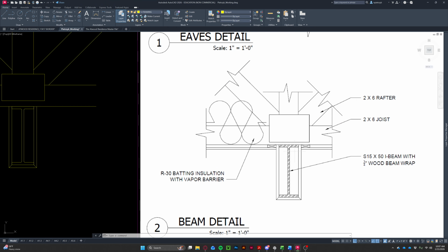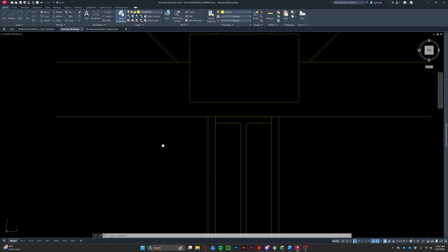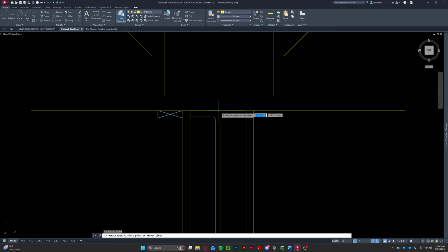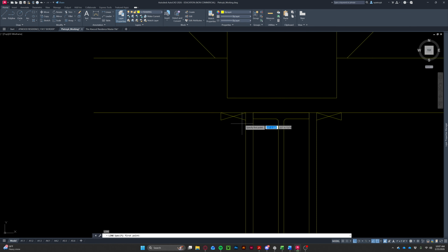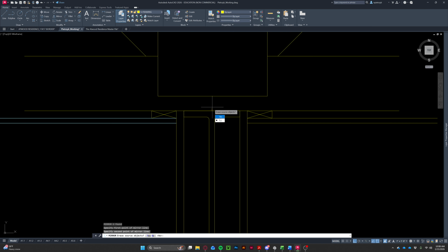I have to do this gypsum ceiling. So I'm just going to draw my furring strip first. Again, it is 2.5 inches by 3/4 of an inch. Up, draw my X. I remove the top and the bottom because they're going to get obscured anyways. Put that there. I'm simply going to mirror this to the other side for ease. Draw a line over, offset 1.5. Oof, offset 0.5 because it's half of an inch. Same thing. Mirror it.